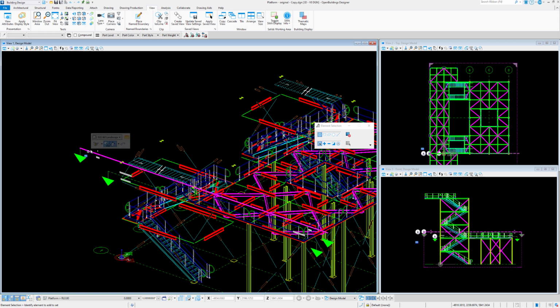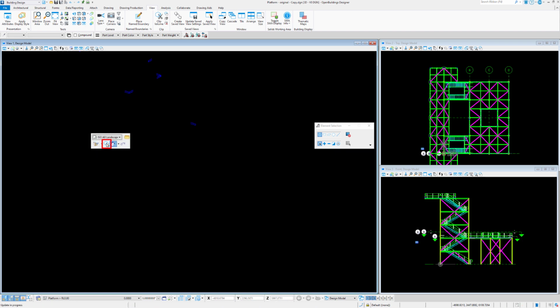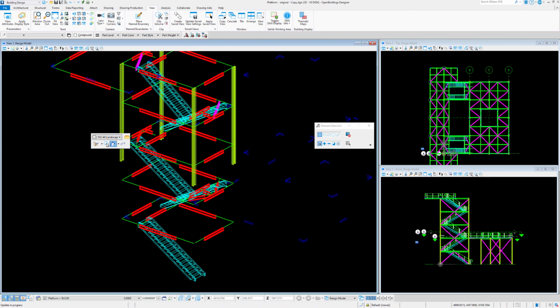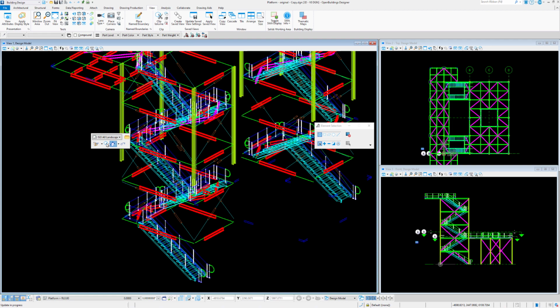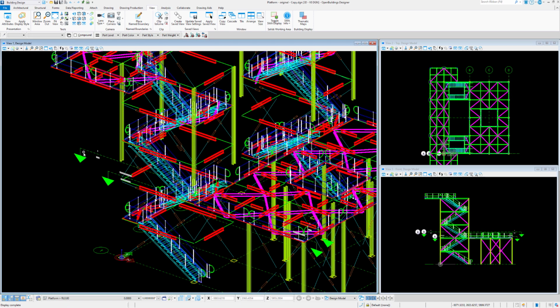If we hover over the callout again, we can turn the clip on or off using the clip tool. If we invoke the clip, we can also turn the callout on, and within that we can turn on either the selected callouts, any intersecting callouts, or all callouts. So we can turn that callout on or off.